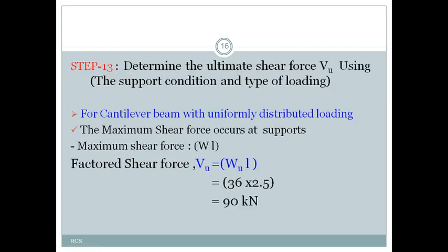Next, we have to calculate shear reinforcement. We have to go for shear design. The shear force value depends upon the loading condition and the type of support condition.